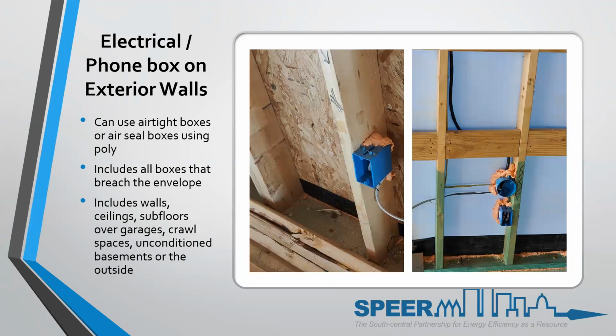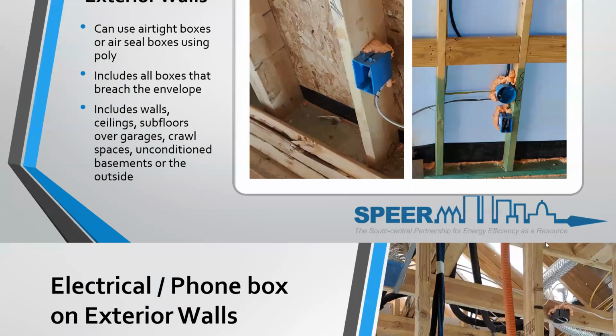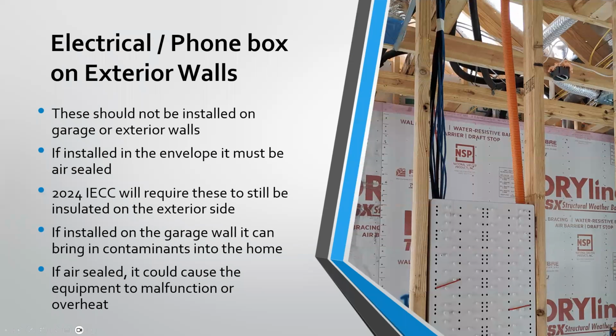It's a building science term of what happens, but a lot of builders look at that and say, why do I have to air seal those boxes when they're on an airtight wall, because the outer air barrier is already sealed? And it's because you want to stop convective looping, period. The easiest way to say it is you don't want air to be introduced into the wall. That also means you don't want conditioned air to be sucked into that wall to act as a convective loop. So you're going to stop convective looping by trying to maintain the same temperature uniformly through the wall, if that makes sense.